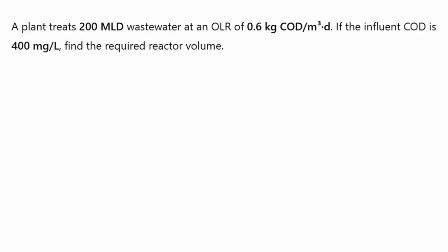Okay, so the next problem is problem number 5. A plant treats 200 MLD at an OLR of 0.6 kg COD per meter cube per day. If the influent COD is 400 mg per liter, what is the required reactor volume?